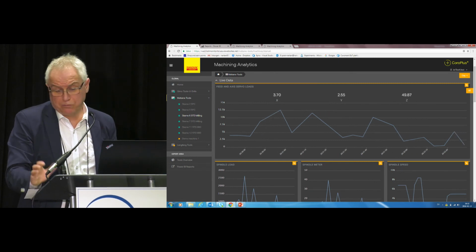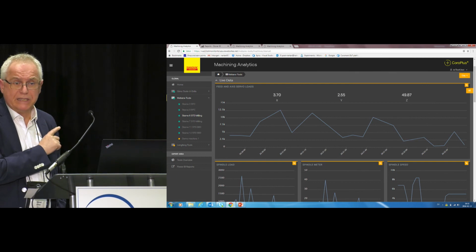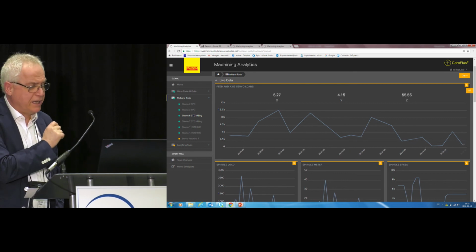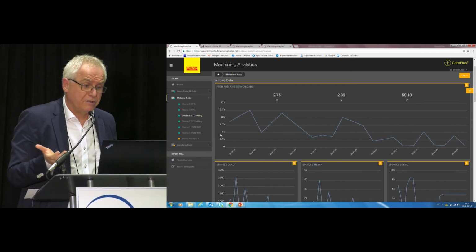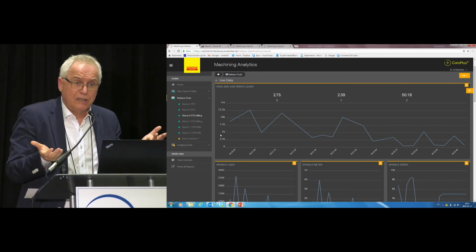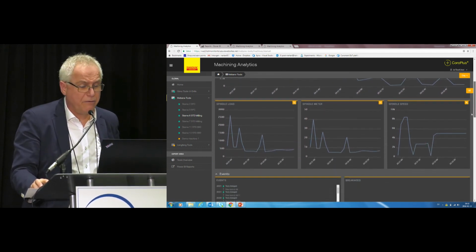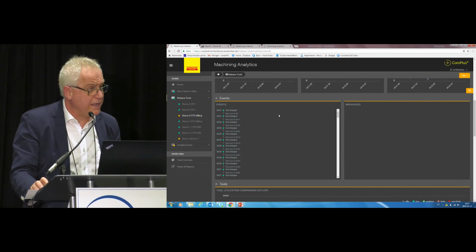You can click on the machines, and immediately we pull the signal from the machine. We pull the signal every millisecond, but we publish it every 5 seconds on the graphics here. These signals we normally check. Very important is the machine spindle feed and speed on the axis and the spindle. We normally look at which speed they have, which load they have on an axis, and whether there are any immediate events.